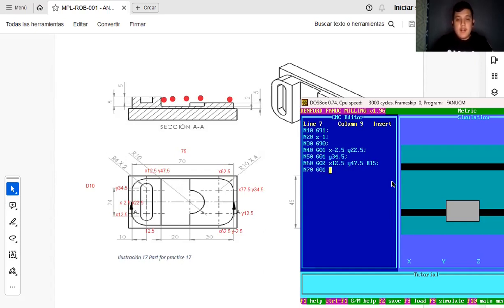Next one is in 0 1 because you have to move 60.5 in X. We're going to do that radius again. We're going to position it in 70.5, X and Y 32.5. And the radius of 50. Now we're going to go down to that point, this one. Then in X 62.5, Y minus 2.5 in the radius of 15.